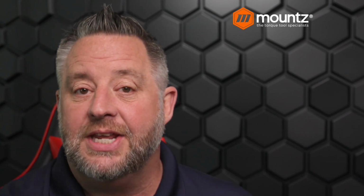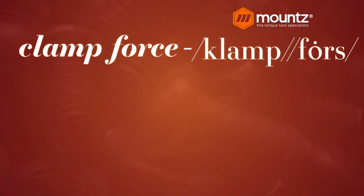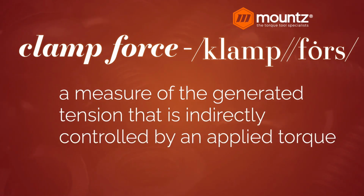Now, when we use a torque tool on an application, torque is what we are measuring or trying to achieve, but the end goal of what we are actually trying to achieve is clamp force. Clamp force is the amount or measurement generated by the tension that's indirectly controlled by an applied torque. So this is what we are really trying to achieve when using a torque tool: tension that allows us to keep components together without them moving.